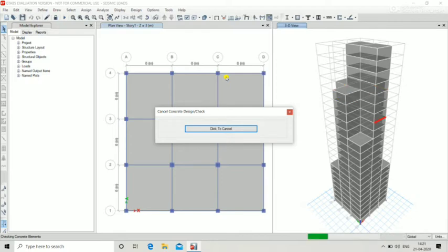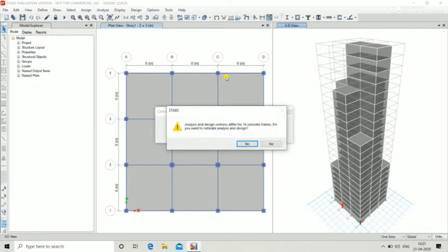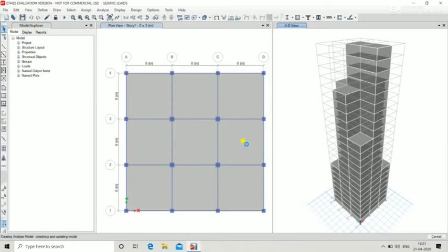In that, click seismic and then modify lateral load. Since we are analyzing using time history analysis, we should provide only one direction, so provide only the x direction, and then as we did earlier, provide the necessary values and click OK. Sorry, there is a change in the menu you should select. Instead of load cases, you should go to load patterns. Okay. Now move on to the load cases menu.